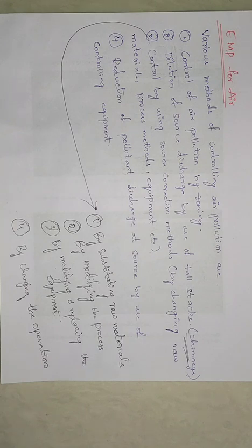Next, we can use low sulfur fuels in place of high sulfur fuels, because it will reduce SO2, sulfur dioxide, in the atmosphere, which is a very dangerous component. The other one is fluorospar, which is used in hearth furnaces. This can be changed by using bauxite flux, and the emission of pollutants decreases because of this bauxite flux.